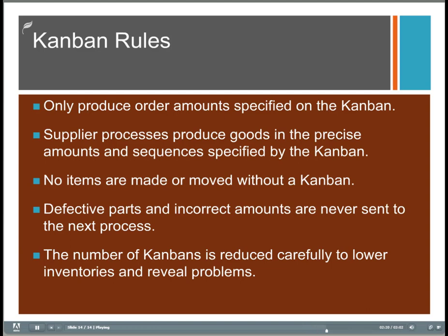In other words, when an order comes in for 1 part or 10 parts or 100 parts, instead of producing them in batches, we're producing them one part at a time through the system, which would ultimately reduce our inventory to an absolute minimum. So one of the movements that's going on right now is to try and achieve one part flow and get away from batches. It's really kind of remarkable when you see some of the one-piece systems that have been put into place.